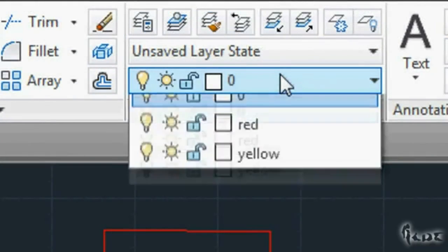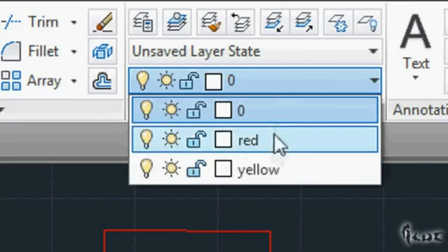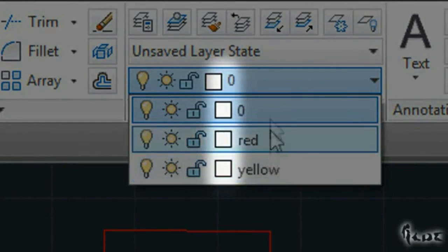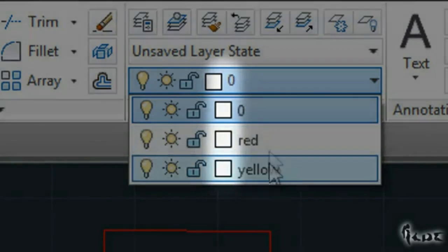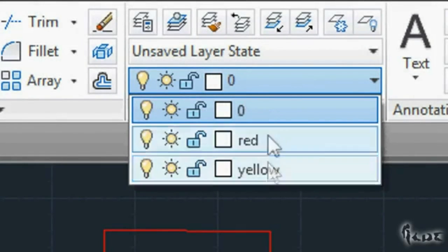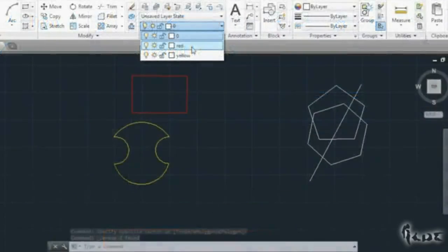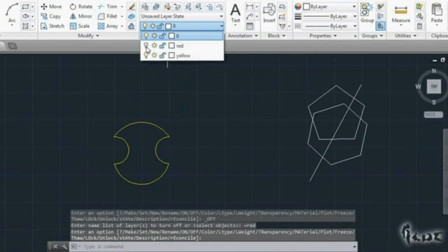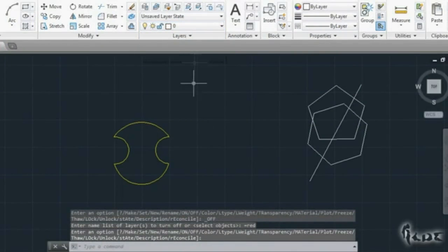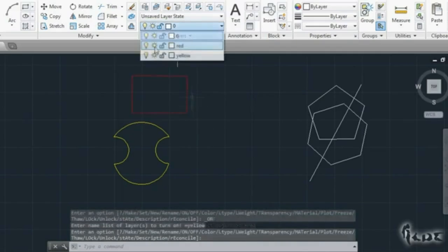You can see in such list 4 different icons. The last one simply says the main color of the layer, which is called by layer color, and next to it its name. The first icon is used to hide or show all the objects related to the layer considered. Hiding all objects of a layer will make them invisible, so you can't edit, move, or see them either.